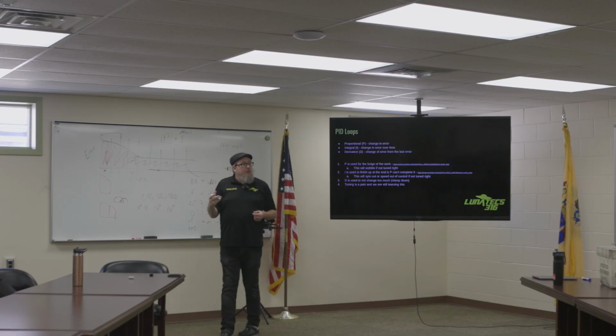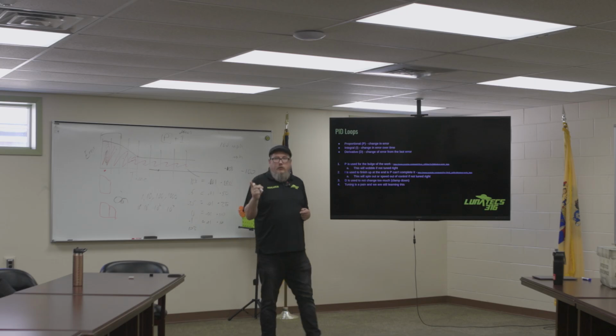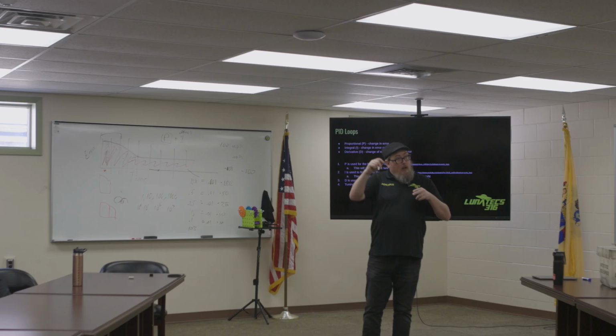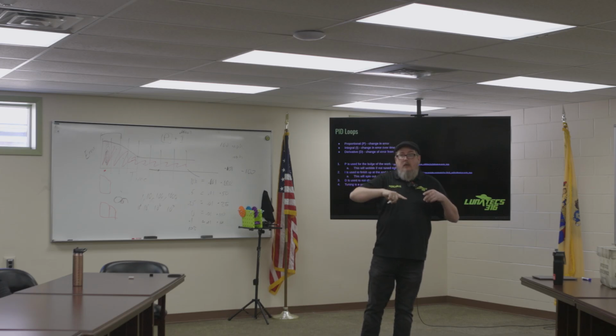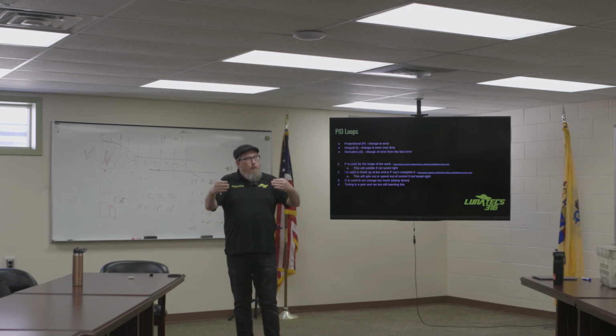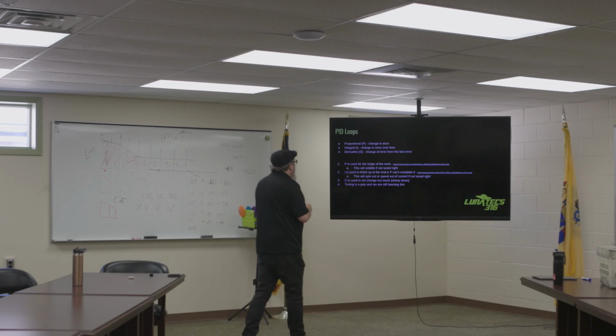If I give -10% power to the motor, what does the motor do? It shuts itself down or puts it in reverse. When we talk about giving power to the motor, positive power will turn it one way, and negative power will turn it the opposite way. So if I overshoot my target, it will naturally correct and back up because I'll start giving the motor negative power, and negative power means go backwards. Does that make sense? Now, I'll show you what an I can do.